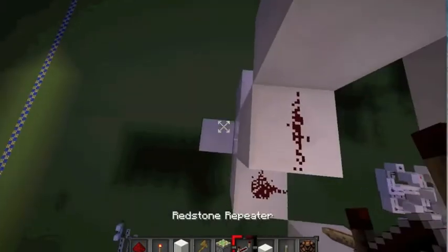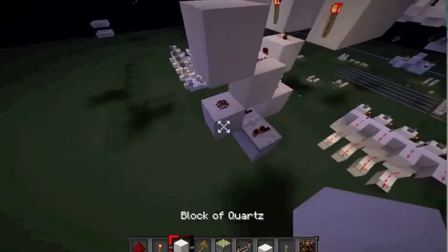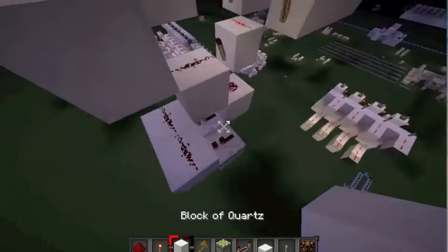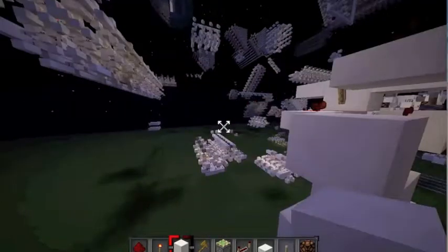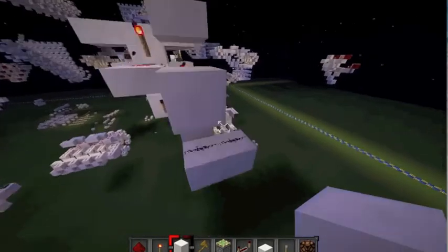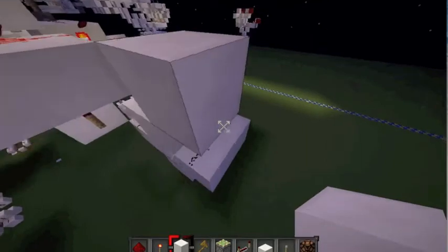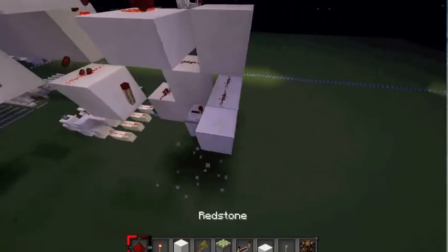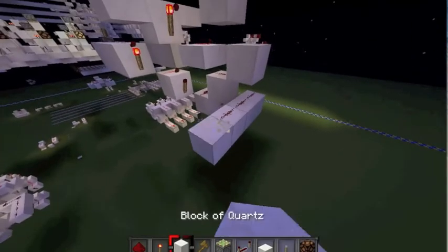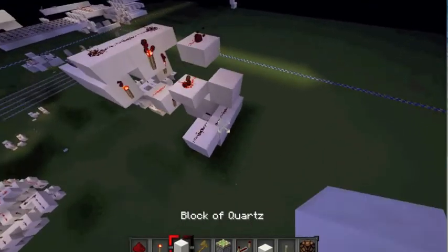Also, when I actually build the flood carry, it's going to be right here, so it's going to flow backward into the first half adder, and then it will just conflict with all sorts of things, which I don't want to happen. So that's why I'm not doing that. Anyways, this is an instant carry adder, as I've hinted at before.